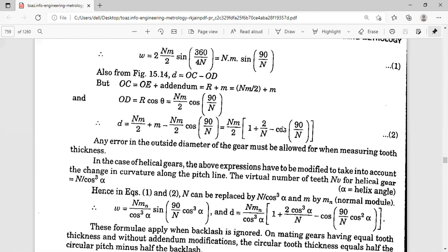And because we are dependent on two readings, what are the two readings here? It is the reading on the horizontal vernier, and also the reading on the vertical vernier. It will not be like an ordinary vernier caliper; it will have a horizontal vernier and a vertical vernier. So we have to depend on two vernier readings, and each one is a function of the other.